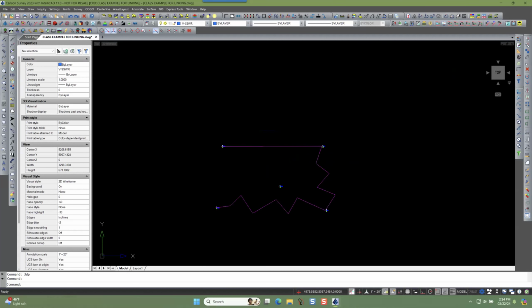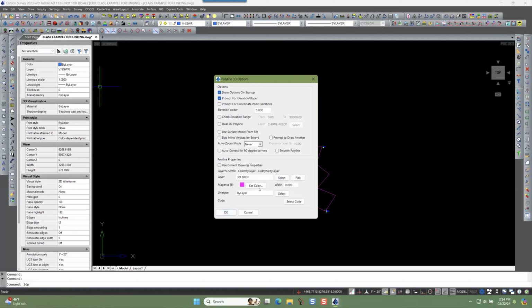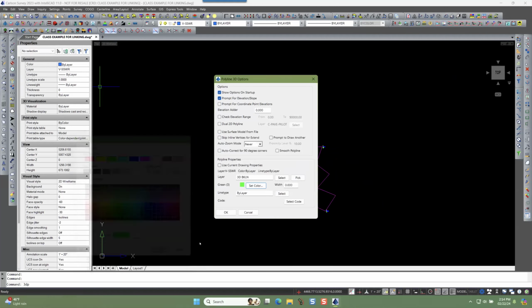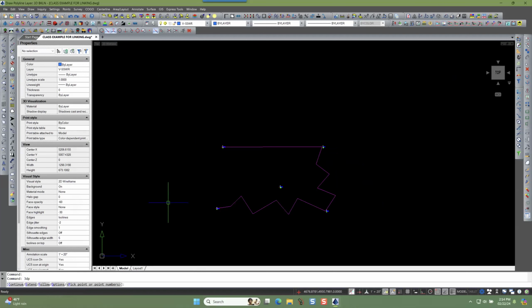We can also do, let's say we're going to go from here. Let's make a new one, a different color. We'll just go the same route. We're going to go from 1 and now to 2. And now I'm going to go off to the side here and I want to put that at a particular slope. I'm going to do it at a percent slope, and that percent is going to be negative, let's say 2.5%. So minus 2.5.